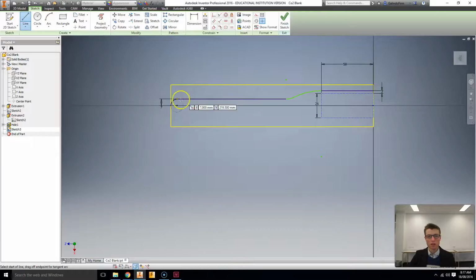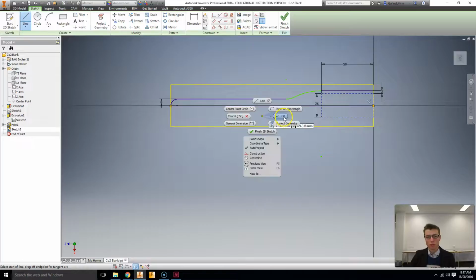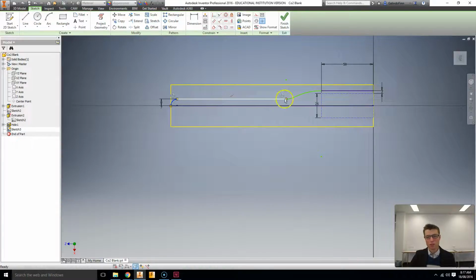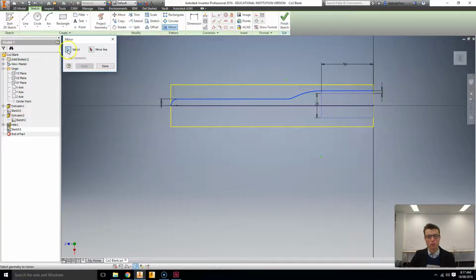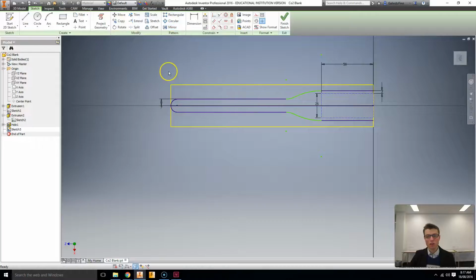I'm going to select a line, and I'm going to click between the two points front to back. I'm then going to select all my geometry, holding Control, just like that, and click the mirror tool. Now the mirror tool has got the selection button completed. It's gone white, but it needs a mirror line, and I'm mirroring it across that line I just made. Clicking Apply, and you can see now that I've got a duplicate on the other side. Now I just need to join up the back edge, and I've got a completed dragster top profile.